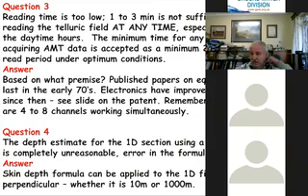In other words, you have a depth range. Although it's not linear, the data is given out as a linear function of the depth. But when you're collecting the data, it is not linear. They're converting that, a pseudo-logarithmic increase in the depth that you're looking at, depending on the time. In essence, the higher the frequency, the shallower you're looking; the lower the frequency, the deeper you're looking. That's where you're looking from about 10 hertz to about 10 kilohertz for these systems.